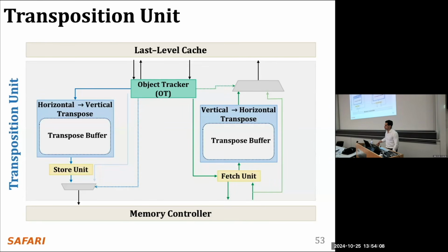On initialization, you would have to write data to the DRAM, assuming the new data layout. When you are just initializing the data, it is going to be written in the traditional horizontal data layout. The moment that the data starts leaving the cache, the data is going to start being transposed, because you don't initialize data inside the DRAM, right? So we initialize data in the cache, in the CPU, first, and then eventually it starts being evicted to the DRAM chip.